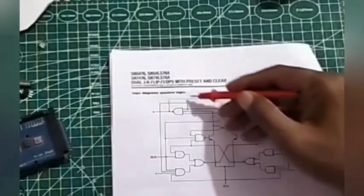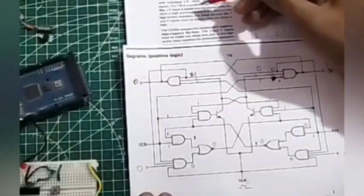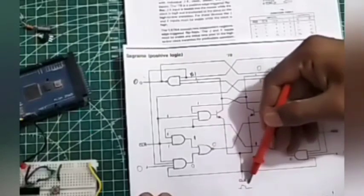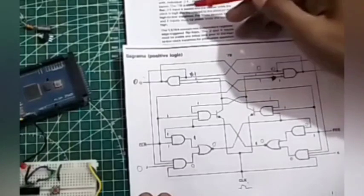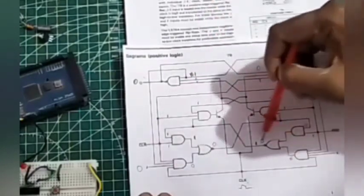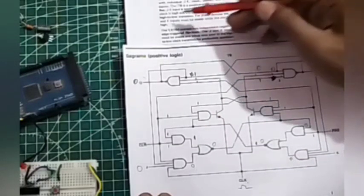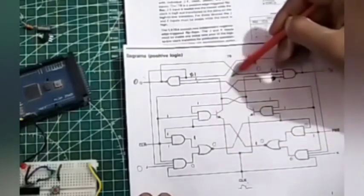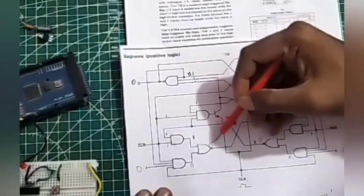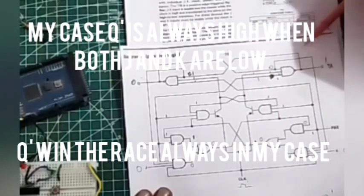This is the master flip flop, and this is the slave. This is the slave and this is the master. This is the positive clock. Whatever the JK input is, it is loaded into the master while the clock is high, and that input is transferred to this slave. If the master output is 0, then Q complement will be high. We'll see it practically.